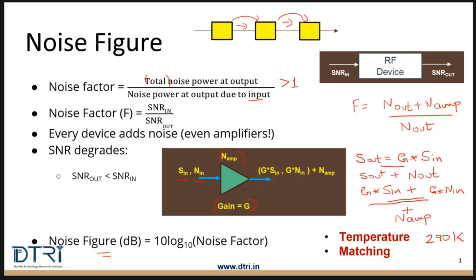Thus, we need to keep these two important points in mind during noise figure calculation, which are temperature and mismatch loss. In practical RF system design, non-linearity and mismatch are a real possibility and thus are considered during receiver system analysis.